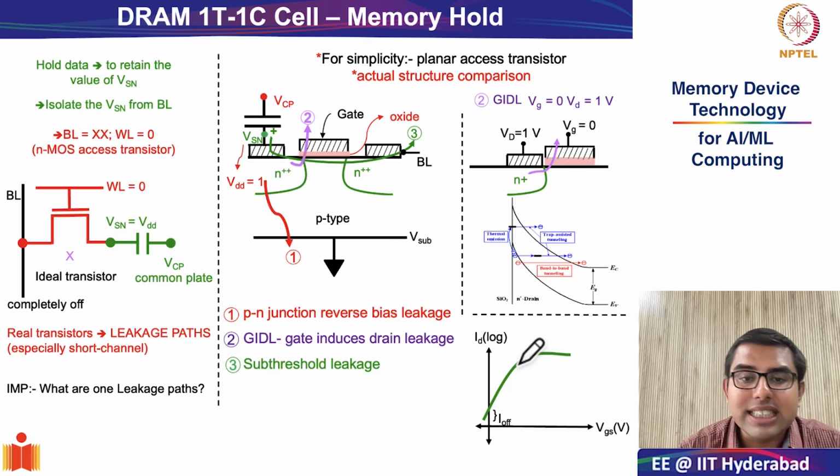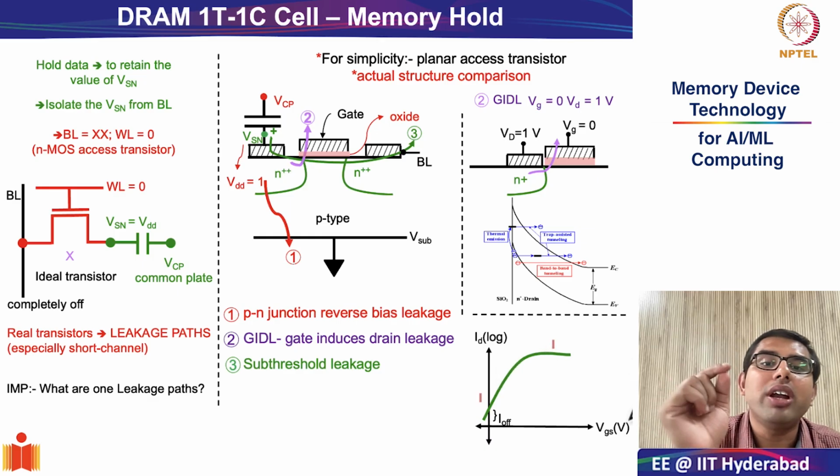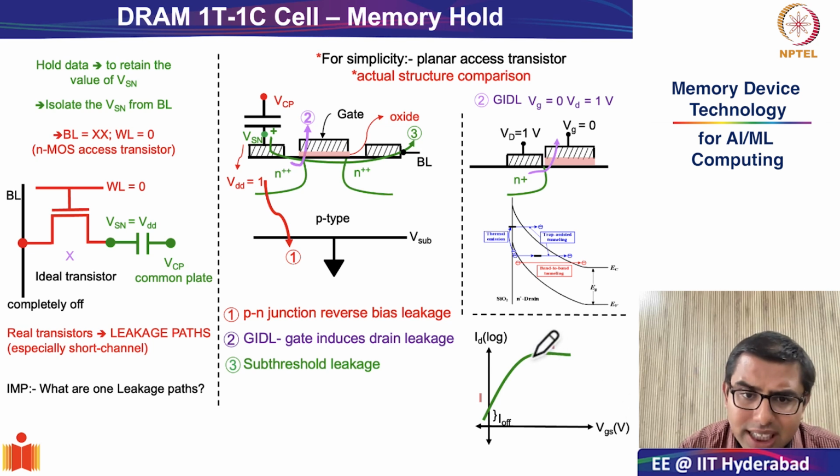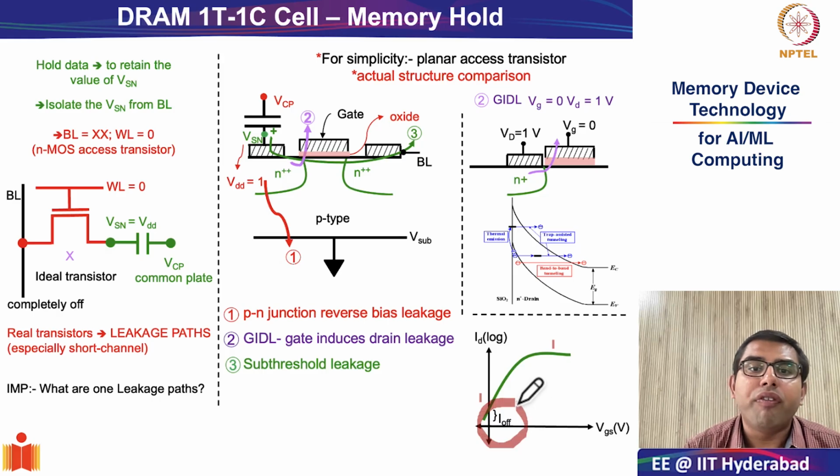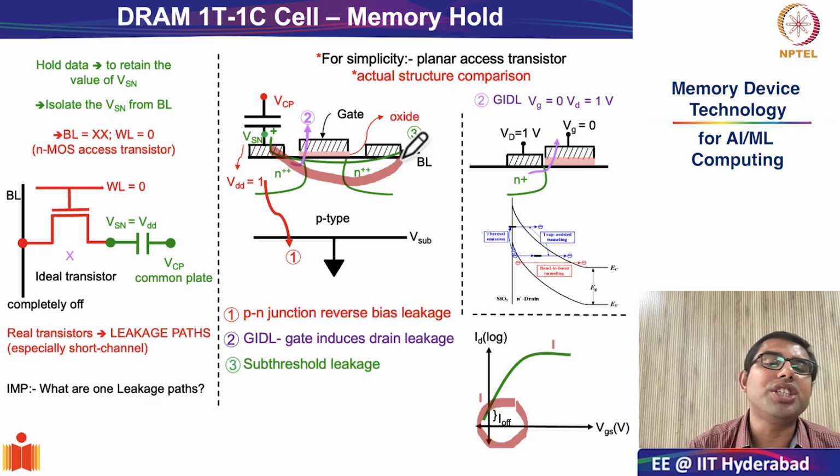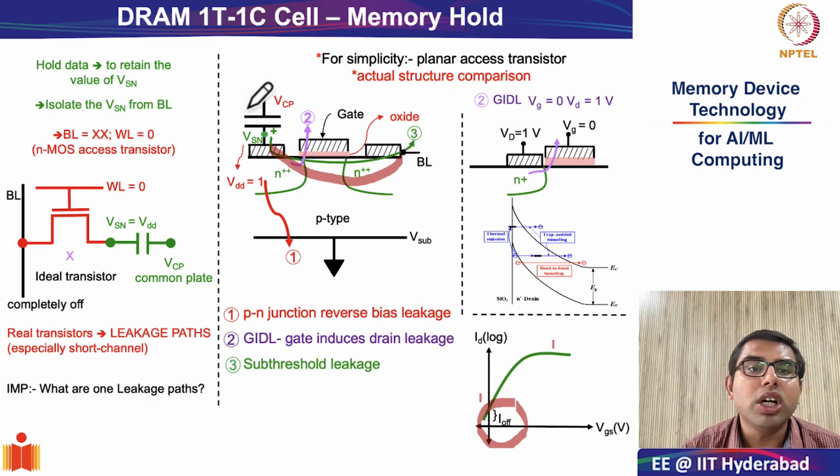Subthreshold swing is essentially the slope with which the transistor goes from the off state to the on state when ID versus VGS is plotted in the log scale. So this results in a finite off current for the N-type transistor. This finite off current, which flows as a diffusion current from the drain to source, is also responsible for leakage of charges from the storage node.